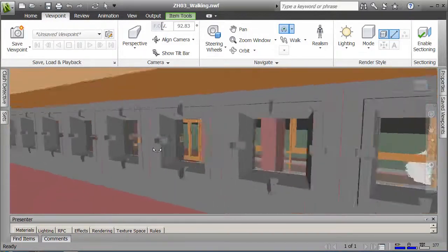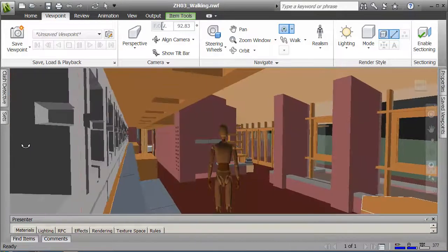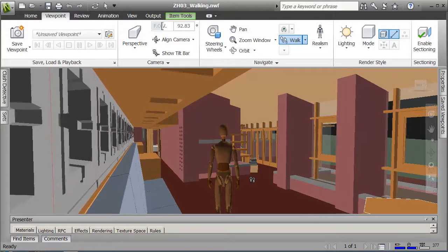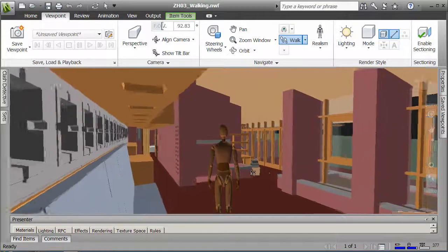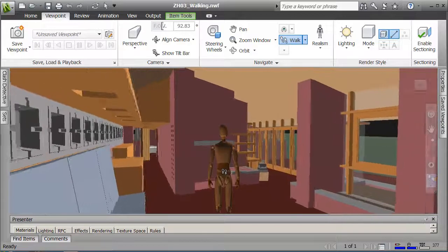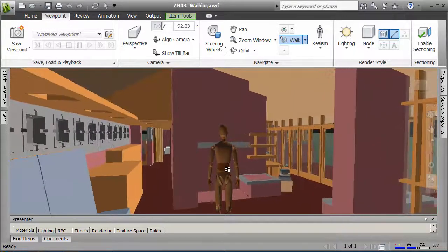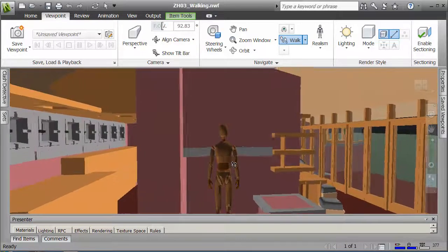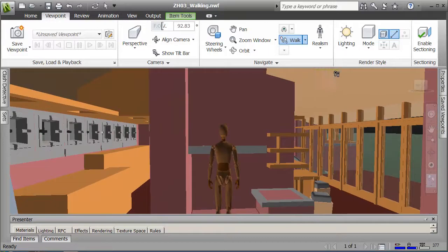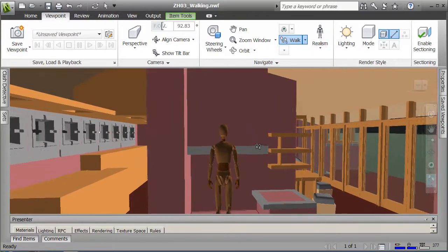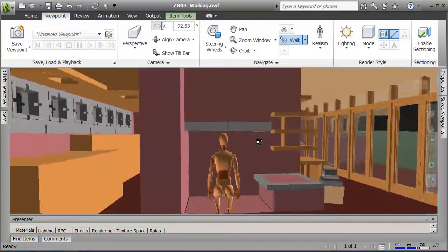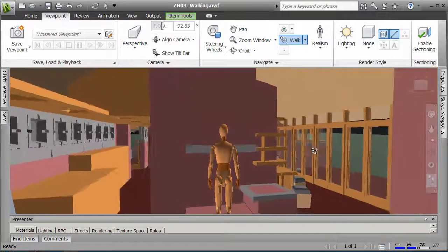And then I'm going to start walking forward again. The product has options on what this avatar figure looks like. You can use the ones that are delivered because you get some additional behaviors from the avatar. For example, here you see I can move through the fireplace because I don't have collision turned on. If I do Control D or I switch on the collision and I move forward, you'll see that the avatar will crouch down to show me that there's a problem with the head height there.